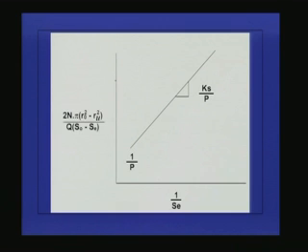So this is the way we usually design the rotating biological contactors. We will be knowing the biokinetic parameters, so using the biokinetic parameters, we can find out the BOD removal the system can have. Based upon that we can find out the number of disks we can provide. Either you provide the disks in a series or provide a series of disks. So that is the rotating biological filters. Nowadays active biofilters are also being used, that is a combination of RBC plus activated sludge process, which improves the efficiency considerably.